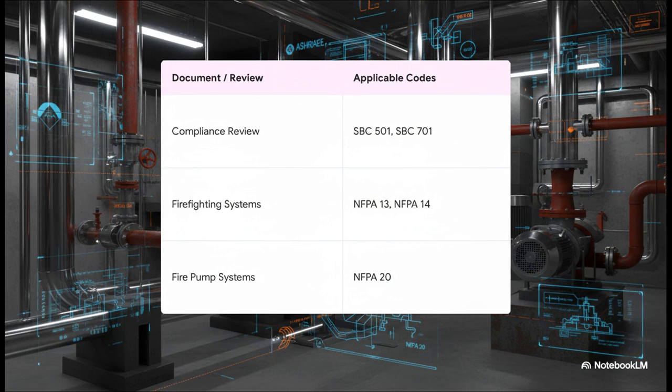Your compliance review can't just be a generic, yep, it's fine. It has to point to specific codes. So for example, a plumbing change might need a check against SBC 501. A sprinkler modification, you'd better be referencing NFPA 13. Being able to name these specific standards in an interview shows a much, much deeper level of understanding.